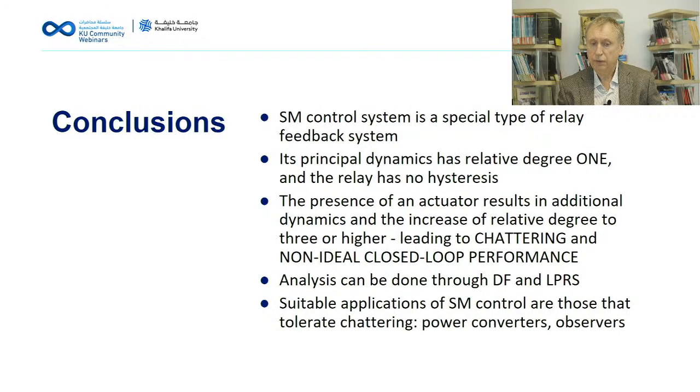Analysis can be done through describing function and LPRS methods. And as a result, suitable applications of sliding mode control are those that tolerate chattering: power converters, observers, and possibly some other systems that can be found, but those two are definitely currently the most successful applications of the sliding mode control.